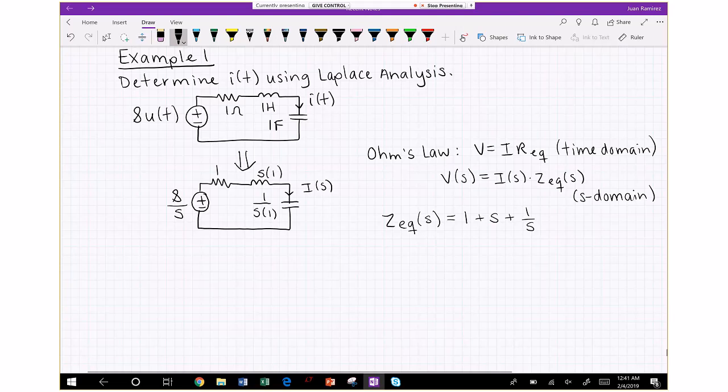You may say, oh, but one of them is a capacitor. Capacitors in series get combined differently. That's true, but it's not true for impedances. It's true if we're putting together capacitors with their capacitance values. Once you look at impedances, you've sort of neglected that way of combining capacitances. So impedances combine just like resistors do.